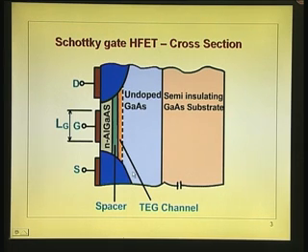It is just about to invert, just inverted sort of thing. So, you have minimum electrons there, and the current will be 0. That means you can turn off this device by applying a voltage across the gate and the source, such that there is a forward bias voltage across the junction equal to delta E c by q.